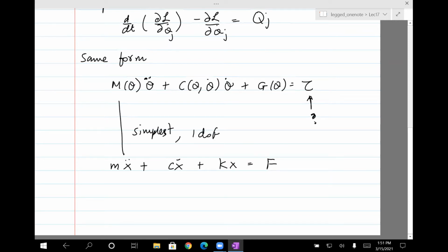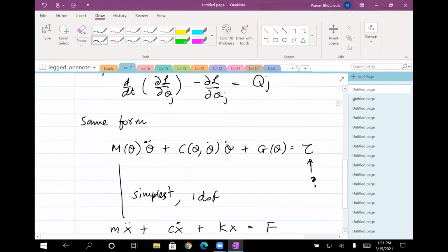This is not a manipulator clearly, but it is an approximation of the manipulator when it is moving over a small delta theta. And in that case, you can actually write this down as a spring mass damper system, if that's easier for you to think about. Okay, so we have the system, which is a spring mass damper system, and then we want to understand the system. And understanding the system, I'll show you, will then help us to control our n-link system very easily. Okay, so let's talk about the system. So let's take the first case of an uncontrolled spring mass damper system.